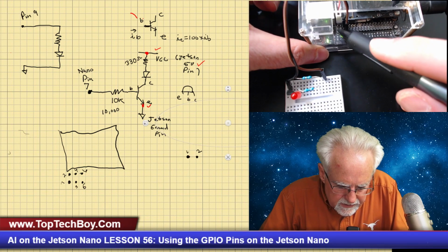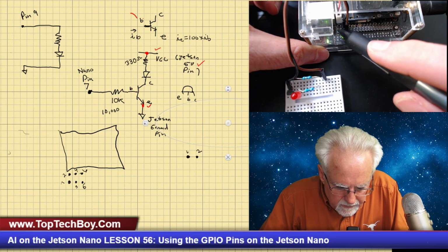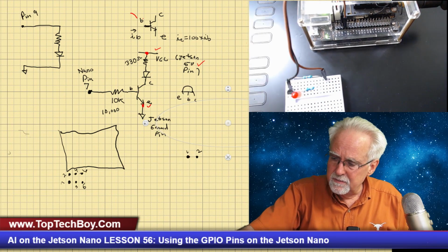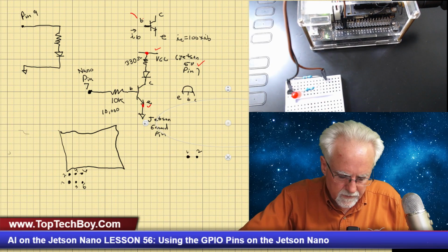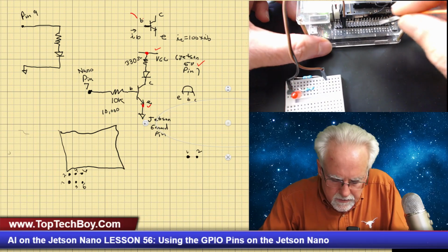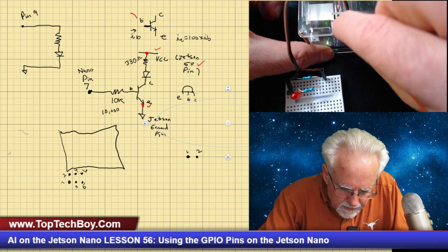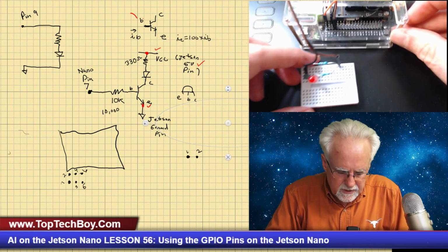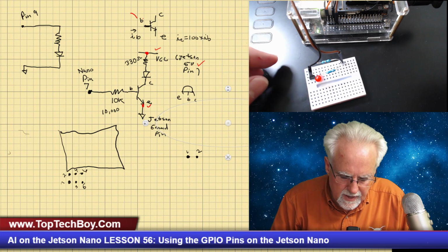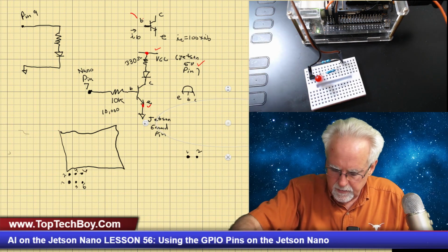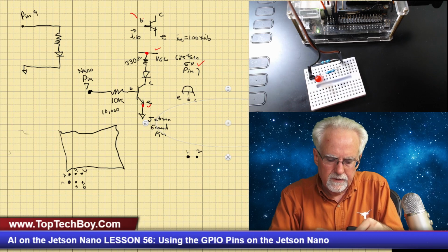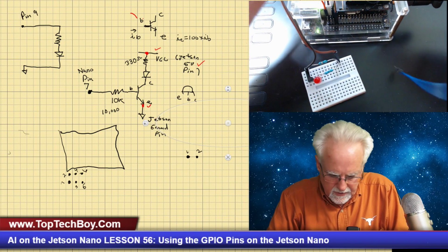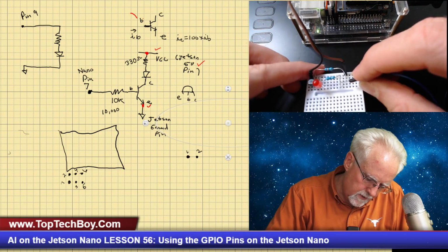And so that is the leftmost column. The inside pin is 5 volts. And you should be able to see that because it's marked 5 volts. And so that is pin 2, and I'm connecting to pin 2. I love this acrylic case, but it does make it a little bit harder to have access to the GPIO pins. So that's the only thing bad about the case. Now I will bring that wire into that resistor.